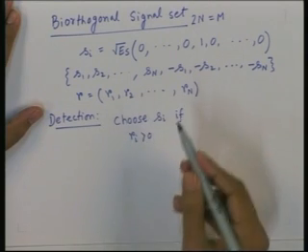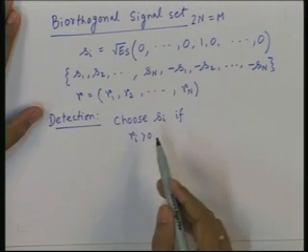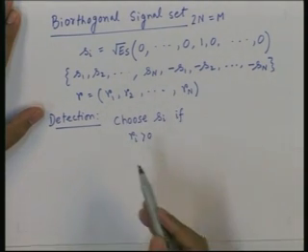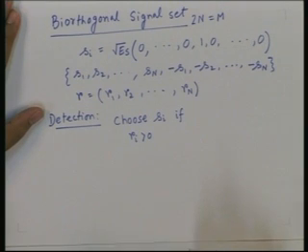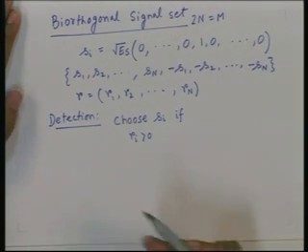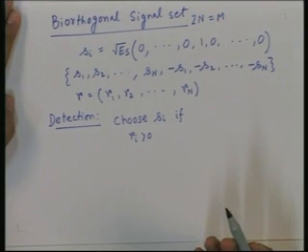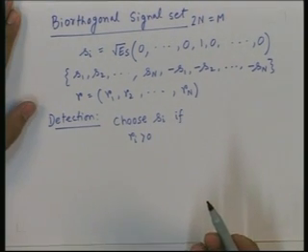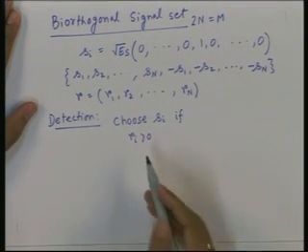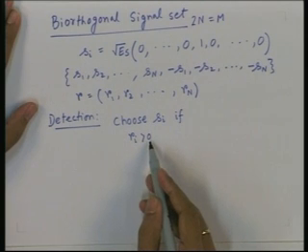If it is not greater than 0, obviously the point is nearer to minus Si than Si. So, there is no reason to choose Si at all, because minus Si itself is a better signal point nearer to the received vector. So, Ri has to be greater than 0.